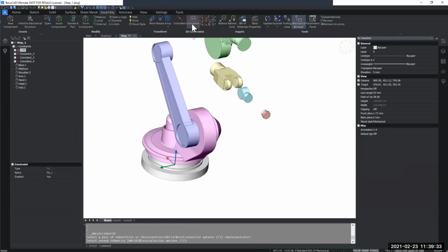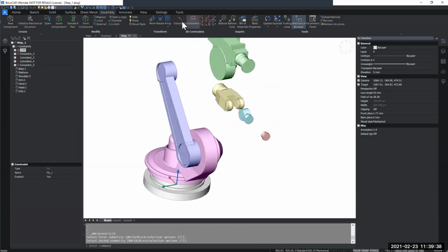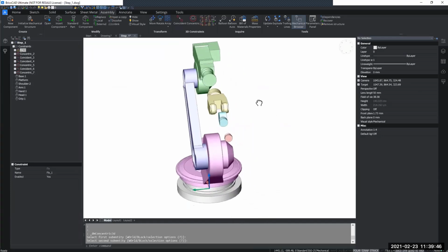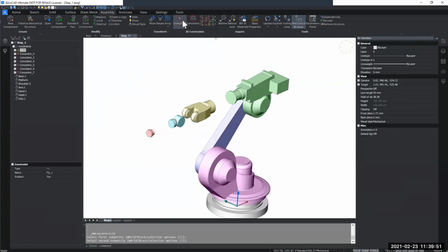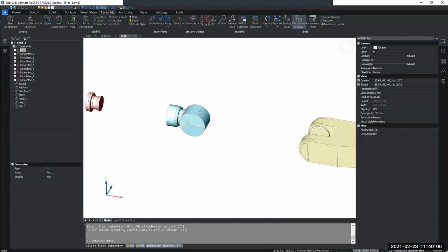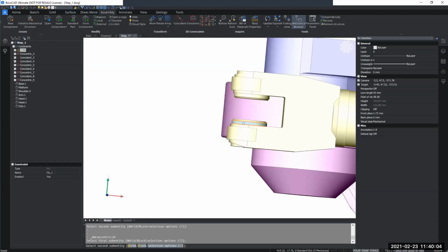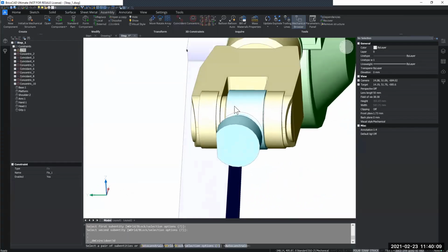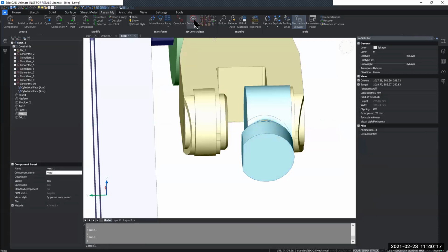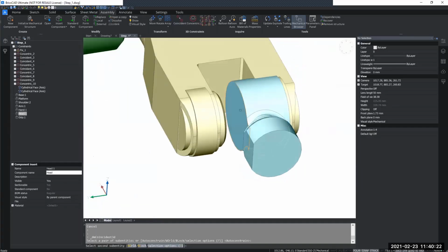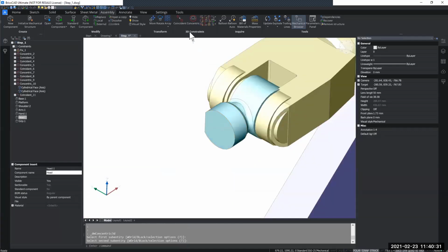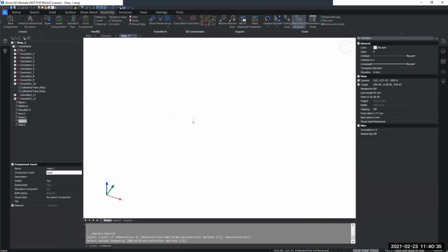And you will be able to use the concentric and coincident constraints on the other parts of the assembly as well. Now we are basically just reassembling the same part that we imported, but of course now it will all be attached instead of being separated. As you can see, you have to be a little bit strategic maybe with where you place the different constraints, but it should be easy enough to figure out where you can apply the constraints. The concentric constraint should of course be applied on circular surfaces, and the coincident should be placed on flat surfaces. Such as this.